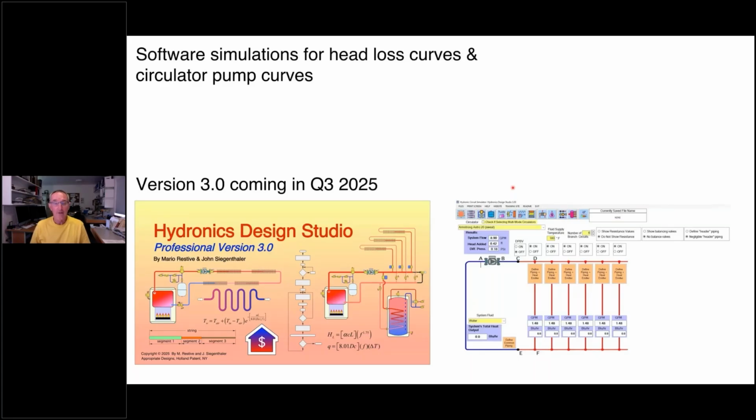You still are going to have to characterize a circuit, though. You're going to have to know, for example, does the circuit have 150 feet of 3/4 inch copper pipe? Does it have 20 elbows? You know, the measurement procedure that we've talked about today is unique because it picks up all the nuances of the circuit. For example, somebody might have put a valve somewhere in that circuit, and for whatever reason, they left the valve half open. Maybe the valve's way off in a crawl space somewhere, you don't even see it. Well, when you test that circuit, the influence of that partially open valve is going to show up.